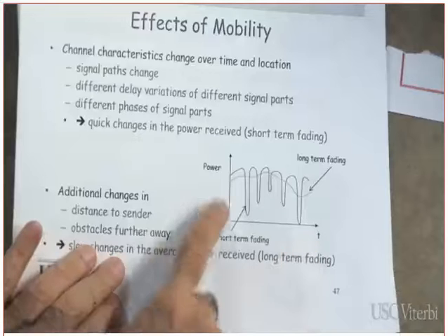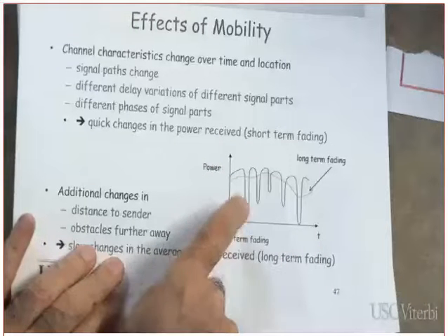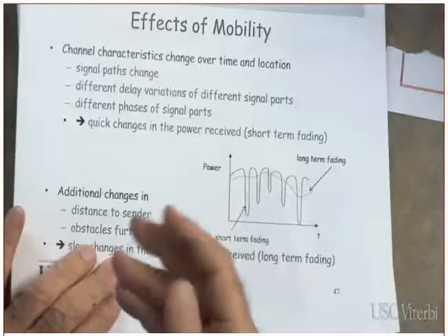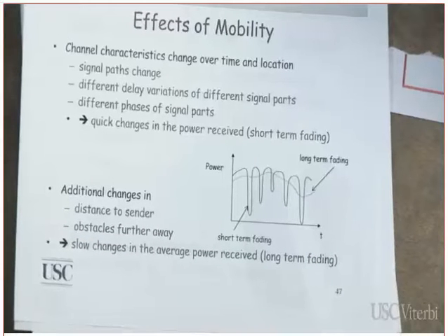Tell me what happened to the signal. At some point, you see this one here? It faded. The signal faded, which means it lost a lot of its power because of cancellations between the multiple versions that you are receiving through multiple delays. Are you following me on that?